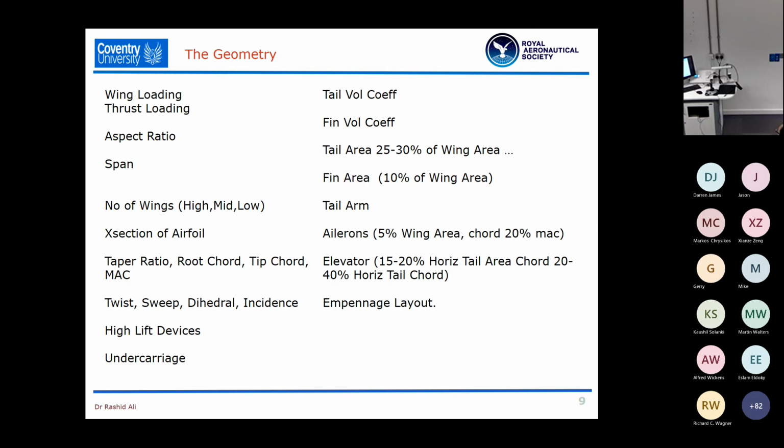Everyone will tell you that if you have a good dihedral on the wing, then they are self-leveling in roll. So a dihedral allows the aircraft to stabilize in roll. So a choice of dihedral at this stage is interesting, but then it poses mechanical issues.